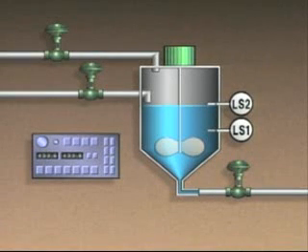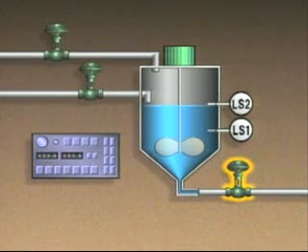The operation of the system in this example is sequential. When one step is completed, another step begins. The programmable controller ensures that the proper preceding step has been completed before starting the next step. For instance, in our example, the agitator's motor must be turned off before the outlet valve is opened. If the valve is opened before the fluids are properly mixed by the agitator, the resulting product might not meet plant specifications.